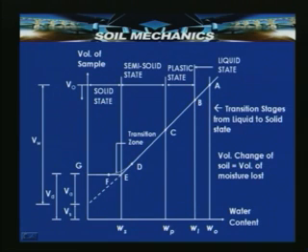This slide shows the different physical states of the fine grained soil. The interface between liquid state and plastic state is defined as the liquid limit, and the interface between semi solid state and solid state is defined as the shrinkage limit. The interface between plastic state and semi solid state is defined as the plastic limit.